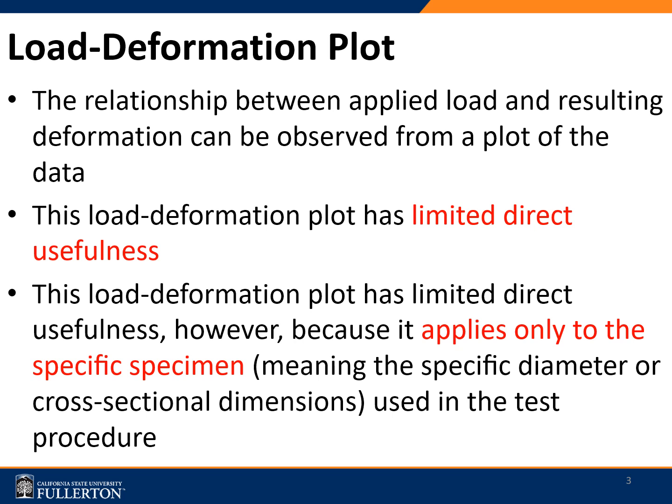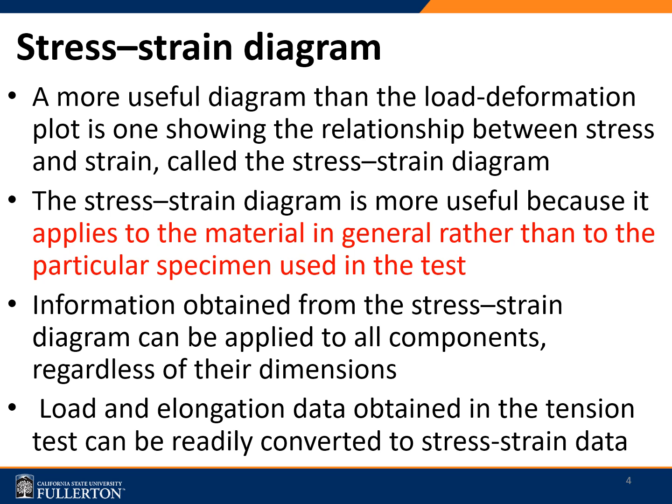The reason being the load deformation plot is specific to that particular sample or the specimen that is subject to the test. A better way to look at things would be to plot the stress-strain diagram, which is derived from the load deformation diagram by converting the load to stress and the elongation to strain.